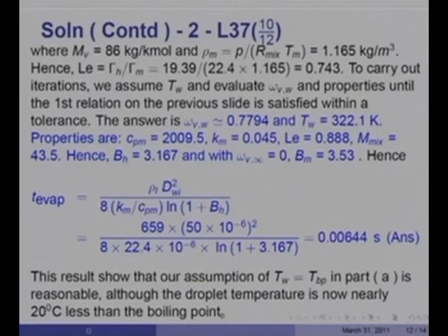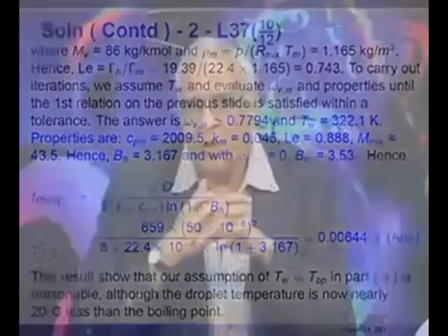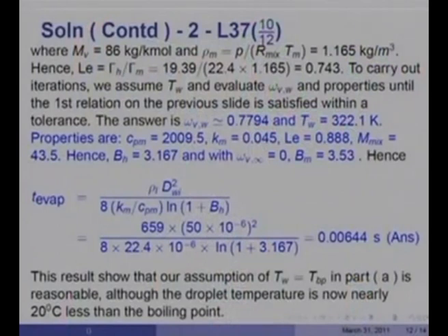Now, this is as far as evaporation goes, but in actual engines this difference of 0.3 milliseconds can be significant, because the total burning time itself is in milliseconds, and therefore 0.3 milliseconds for evaporation is a significant quantity for engine applications. But here, in order to study evaporation of a volatile fuel, what we have done is taken the environment at 850 K to comprise nitrogen.